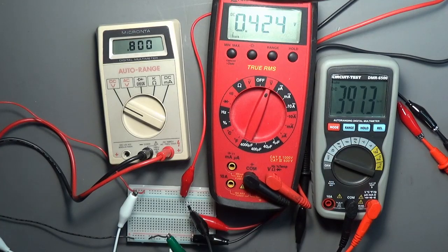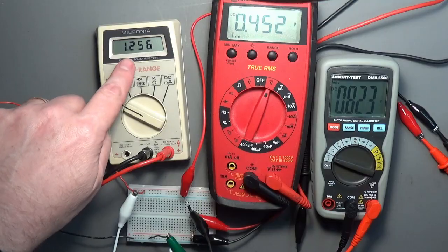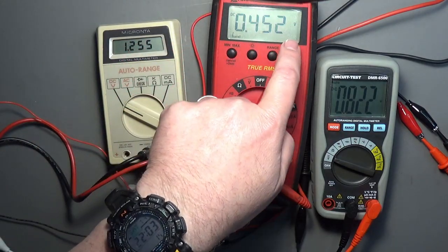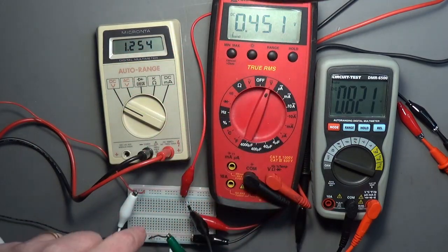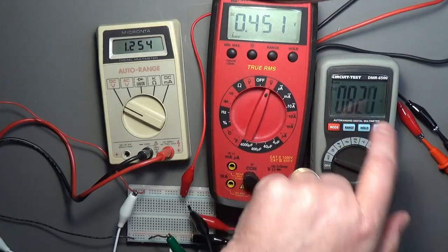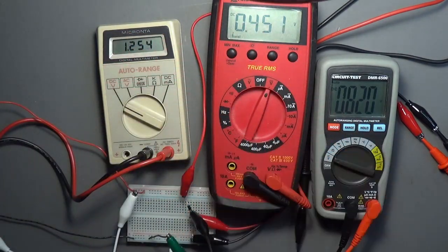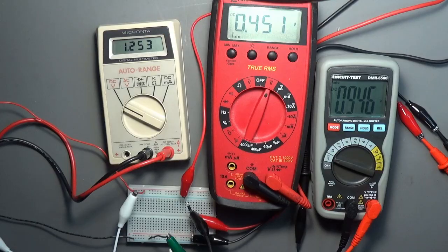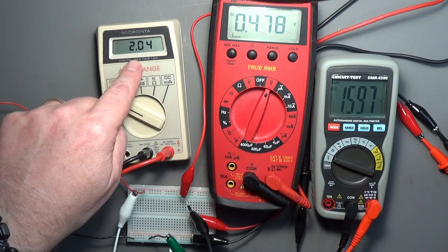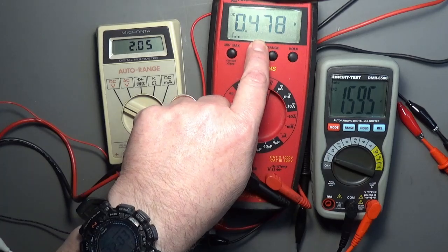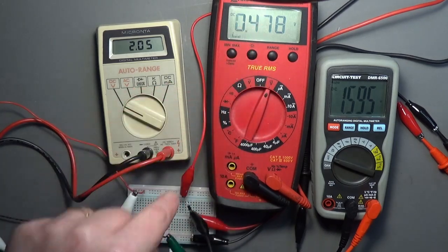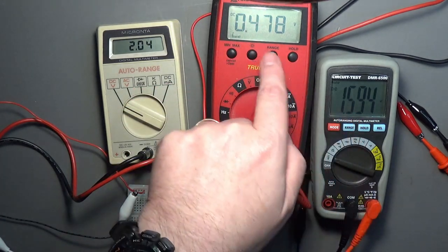So if we bring this up to, let's bring this up to a full volt, a little bit more. We're now losing about, there's a voltage drop of about 0.4 volts across our diode, and we're now at 0.8 there. So which is obviously that minus that gives us that. Let's put this up to 2 volts and see what we get. Okay, we're now at 2 volts. So we've got a 0.478 voltage drop across our diode, and then the difference shows up there.